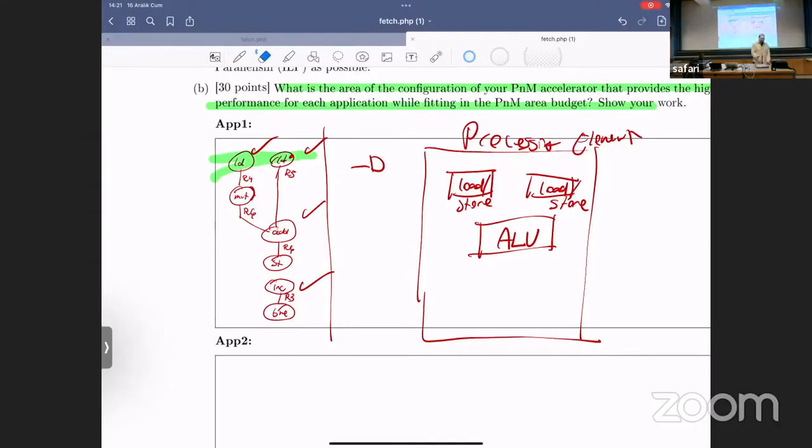The answer is going to be 25 processing element units. If you save one unit in a single processing element array, you still cannot add another one. It's not going to give you 26 processing element units because of the total area. You're saving area, but you could exploit more parallelism if you used that extra area. It's just there. But yes, you could do that.